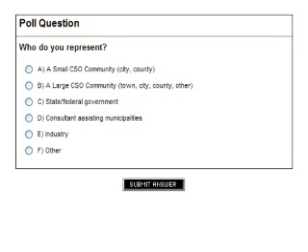But the 4 overflows per year is the presumptive approach type thing. That is not a permit requirement, but on average they should have no more than 4 overflows per year that don't get into the tunnel. That means even those 4 overflows are treated for bacteria. They're disinfected and dechlorinated. So it's a very dilute waste when you get to that level, and it is still treated. So they're pretty much treating everything in Atlanta.